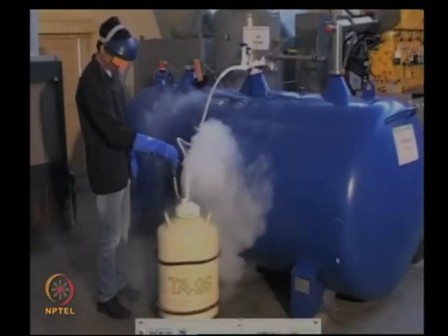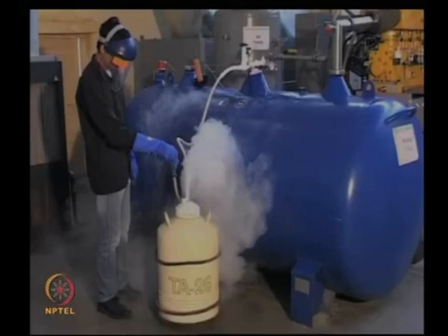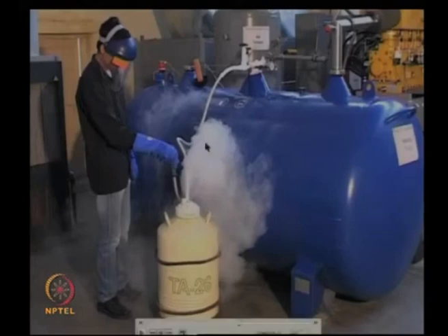You should see that nobody is on this side. This is completely open space, so that nobody faces the boil off of liquid nitrogen, nobody sees it directly, nobody puts their hands on the boil off, and nobody is exposed to it. As soon as you transfer liquid nitrogen, because the vessel is warm, the boil off will be much more in the beginning, and also at the end when the container gets full, the nitrogen may come out. Therefore, you should be very careful in the beginning and at the end.